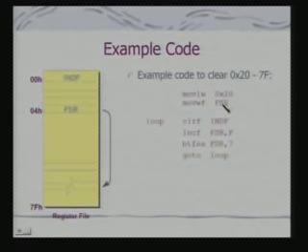As you are going through the loop, what are you checking here? This will do a skip when it is set. So, this loop will not be executed when you have reached 7F. If you try to increment beyond 7F, you will skip, otherwise you will be clearing the content from the 20 to 7F locations. This is an example of using indirect addressing.